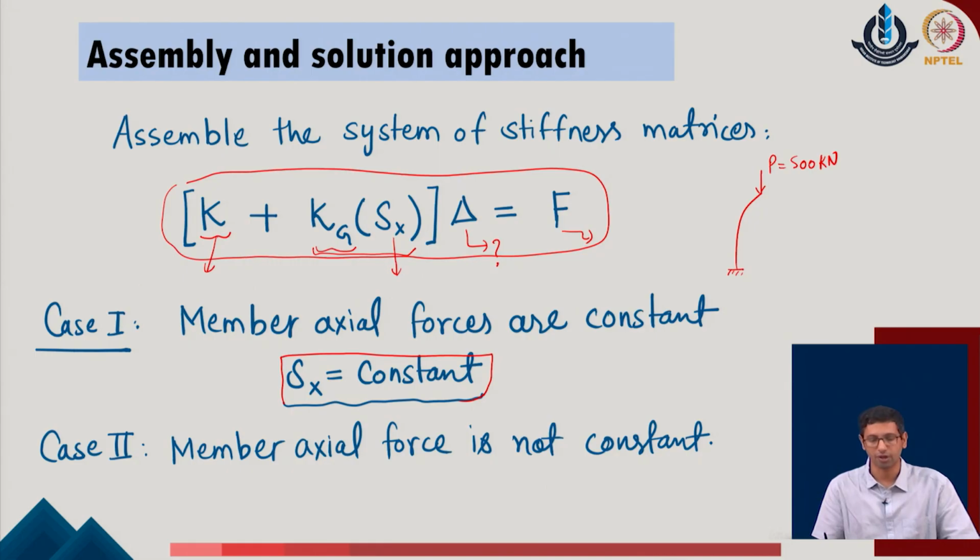As a next step, one has to go with iterations to check whether the effect of this force, active on the given compression member or the column, with respect to the given lateral drift, is included as an additional moment on the system, and whether that affects the overall analysis or not. So, this is one easier way to implement the system, an iterative method where S of x is constant, but we are able to evaluate the response of the system with an iterative scheme.